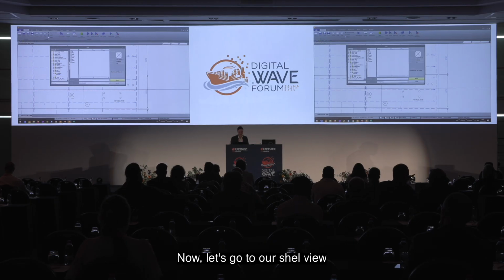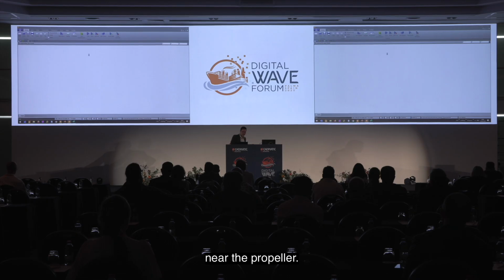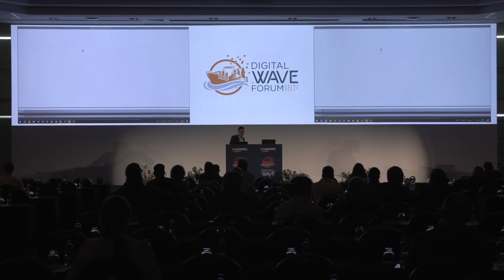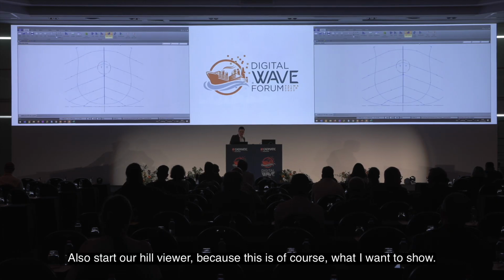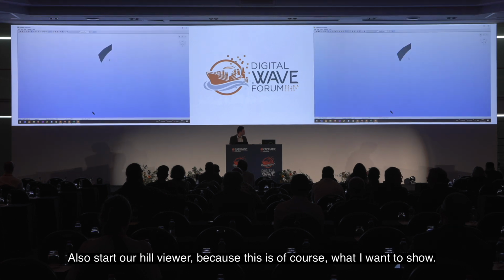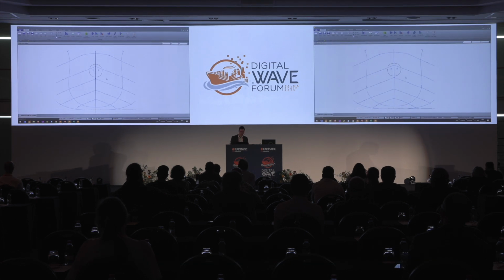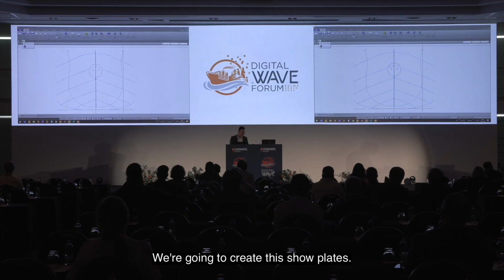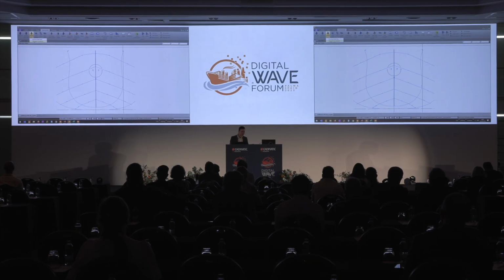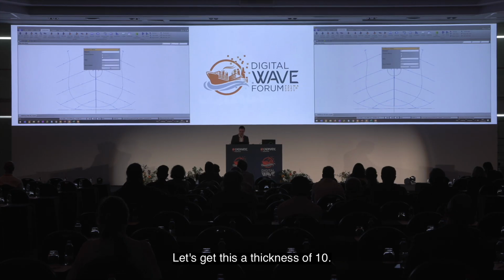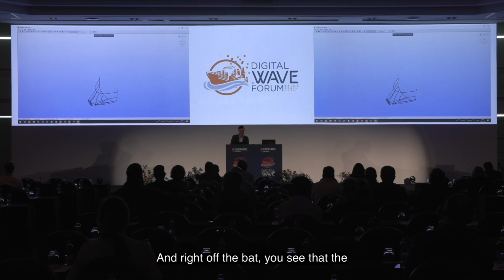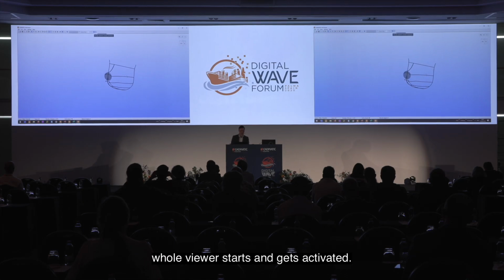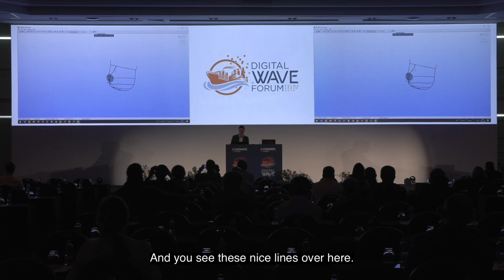Now let's go to our shell view near the propeller. Also start our hull viewer, because this is of course what I want to show. We're going to create this shell plate. Let's give this a thickness of 10, default material. And right off the bat, you see that the hull viewer starts and gets activated. And you see these nice lines over here.